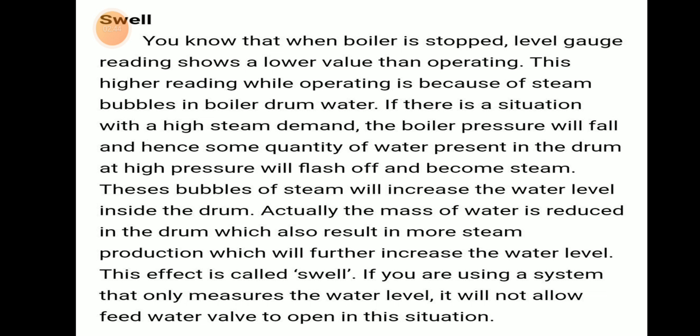If there is a situation of high steam demand, the boiler pressure will fall, and hence some quantity of water present in the drum at high pressure will flash off and become steam. This bubble of steam will increase the water level in the drum in the form of bubbles.